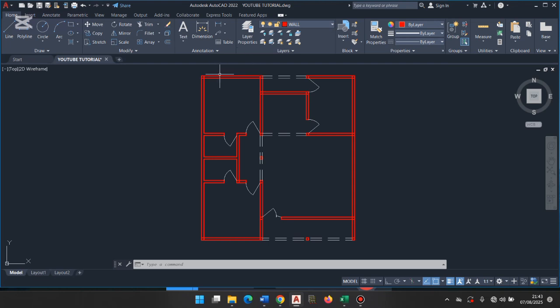Like I said, there are various ways to do that, but for tonight we're going to stick with one method, which is to draw, first of all, the total length of the room or wherever you are dimensioning, and then subtract the width of the window. When you're done subtracting, you divide the remaining value by 2 so that the window will be centralized.